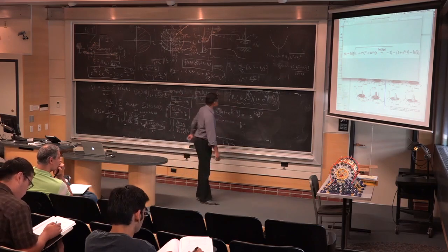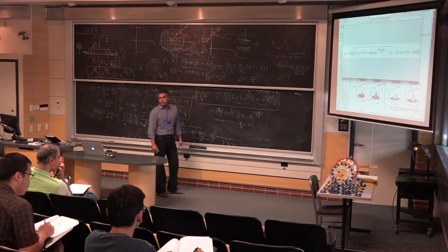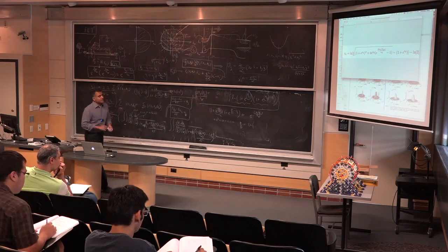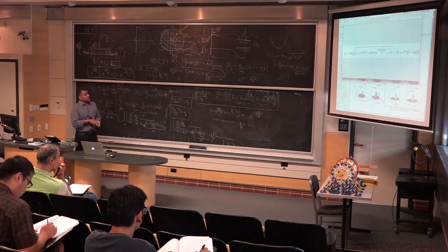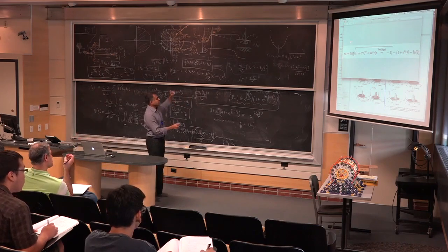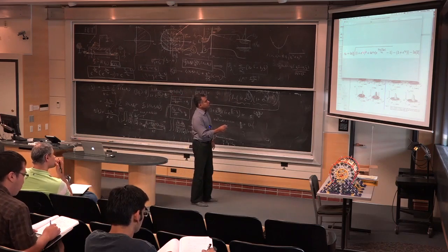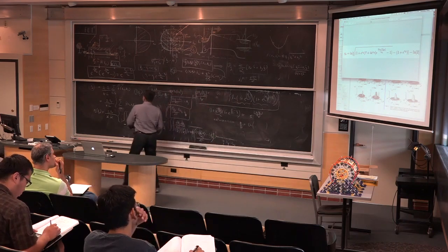So eta sub s is natural log of something, and this is something you can plug in and plot. So what's sitting in there is eta sub s, which is the source degeneracy function level, depends on the drain voltage as v sub d, which we defined.